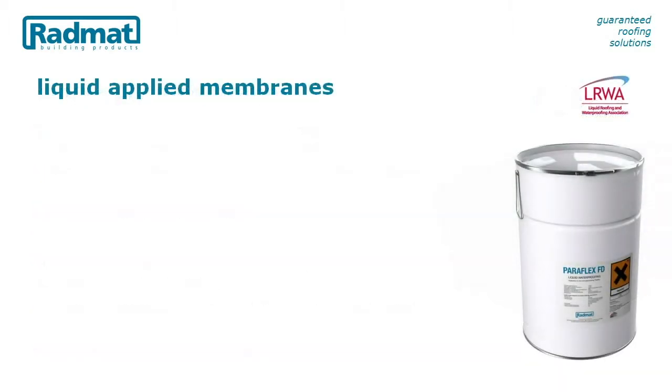Most commonly used in refurbishment applications, cold liquid applied membranes. Many are also suitable for inverted roof application, but as with single-ply membranes, puncture resistance for the applied thickness should be checked. Similarly, BBA certification for zero falls application should be checked, as there are many different types of liquid applied membrane, and it doesn't follow that because one generic type is approved for one manufacturer, it is automatically certified for another. Many different types can be difficult to compare apples with apples.